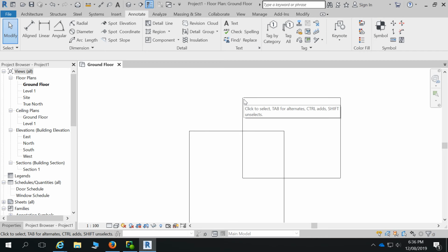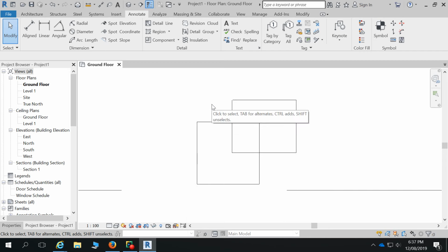As we start drawing in this session and coming sessions, I might come around and say to you, turn thin lines on, because I might notice that you're drawing in thick lines, which makes it a bit more difficult to see how accurate you are. So it's just TL to toggle between the two. That's probably your first shortcut that you're going to start to get used to, TL, and you'll see it on the screen change in front of you if you're thick or thin. Okay.